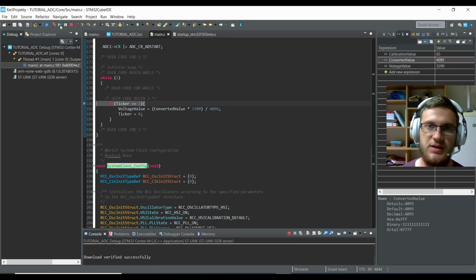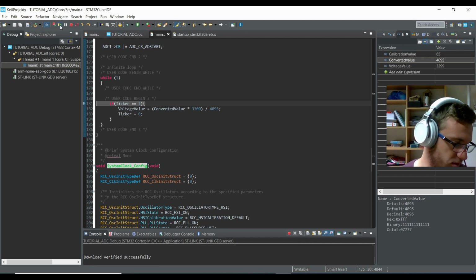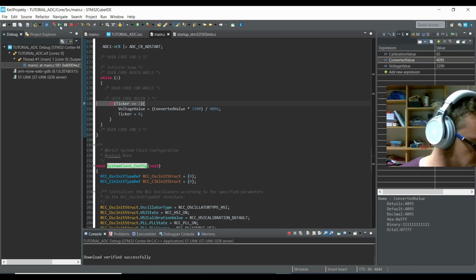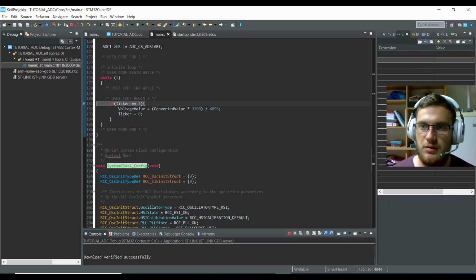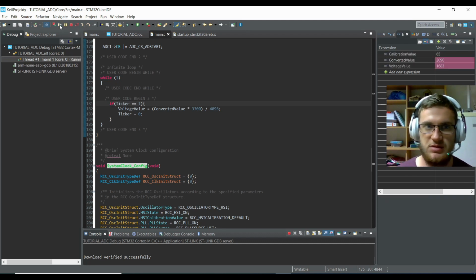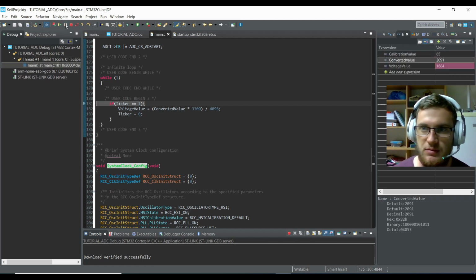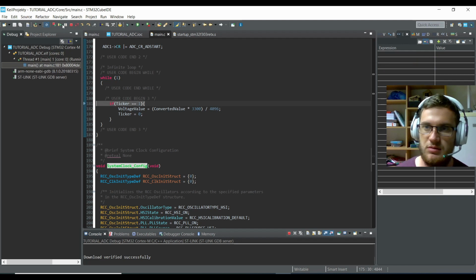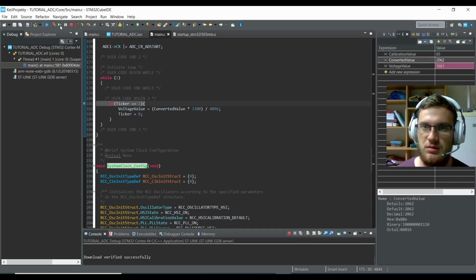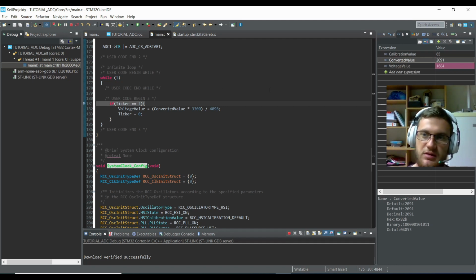Actually, if I play, we can see that the ADC has actually some spread of values. I will turn it, for example, to more or less 50%. Why am I saying more or less? Because my trim pot is not very accurate. It has only a 180 degrees turn. Yeah, we are more or less at 50%. You can see that the value jumps a little, but it's okay. You can read a potentiometer, things like that.